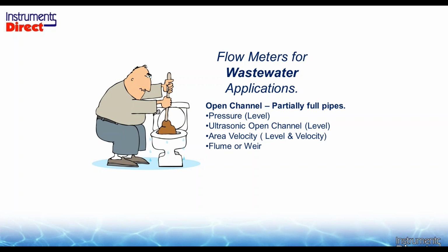So there are no pumps in the system, or there may not be pumps in the system as it flows down the line and may be collected at a lift station, or open channel applications. And to solve these problems, you can use the good old flume or weir and just measure the level with a tape measure or a ruler, or you can use ultrasonic level, and you can also measure level by monitoring pressure, and then use, say, the Manning equation to calculate how the liquid's falling downhill, or an area velocity method, which combines both level and velocity to calculate a volumetric flow.